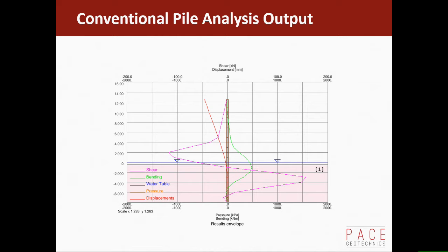And shear, and basically, when you've got all the analysis correct, you press a button and you get that graph. But it is an iterative process because you've got to check your stress in the pile from the bending moment to say, okay, the pile has the capacity to withstand that bending moment, and as you make the pile stiffer, you'll change that curve. So the response will change as the pile becomes stiffer or less stiff. Okay? All right with that?